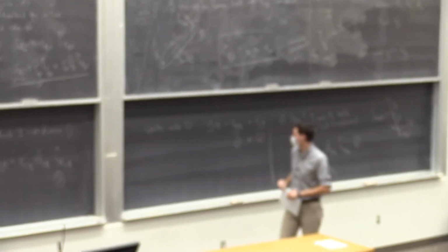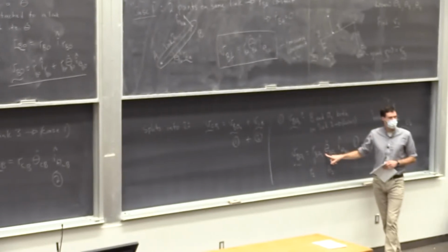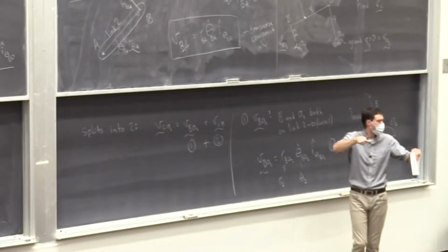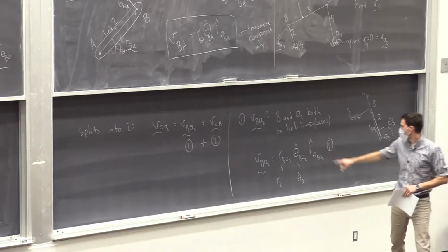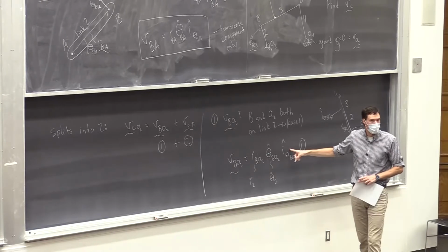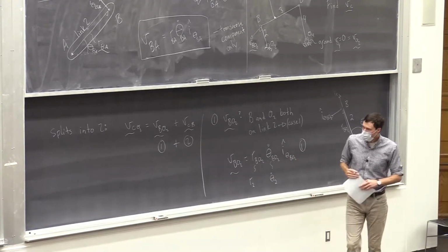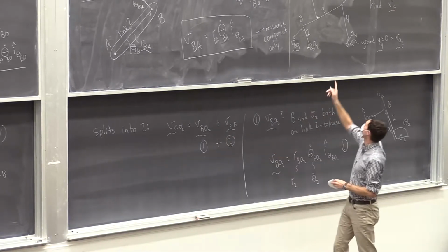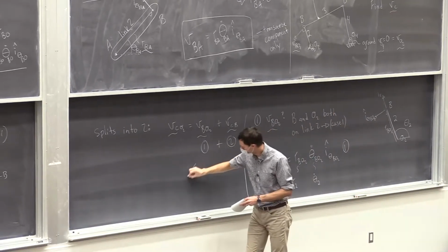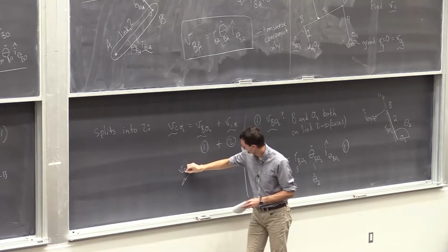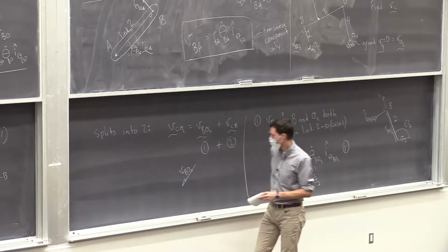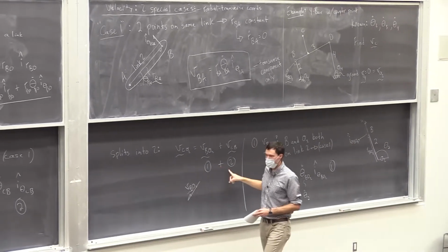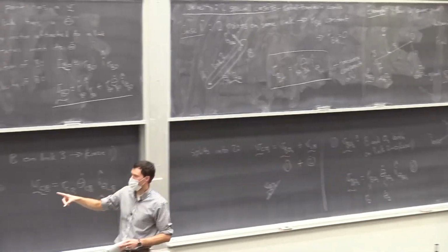Okay, and if it's a graphical problem and you wanted to give actual numbers in here, you could measure all these things, right? You're given the rotation rates, theta dots. The distances you could measure on the diagram, or they'd be given to you maybe. And these directions you could measure on the diagram as well. And you would get something that looks like, let's sketch it out. It's going to be down and to the left. Okay, that was BO2. And on the end of that, we're going to add this new one, which is up and to the left.